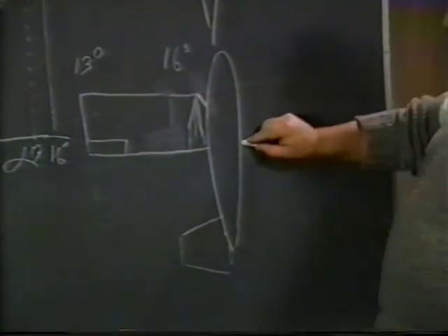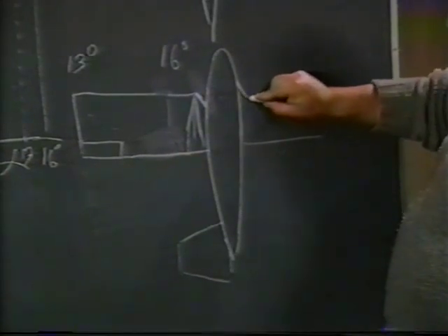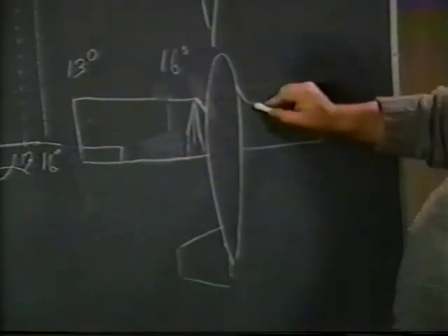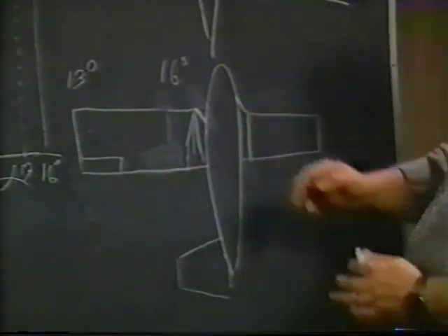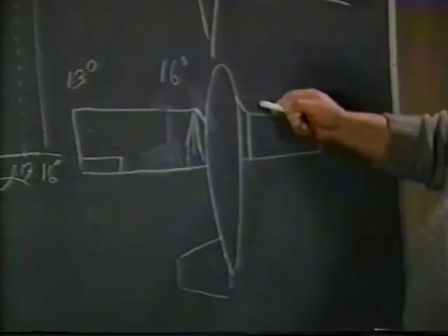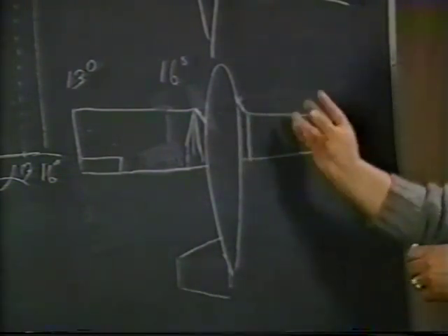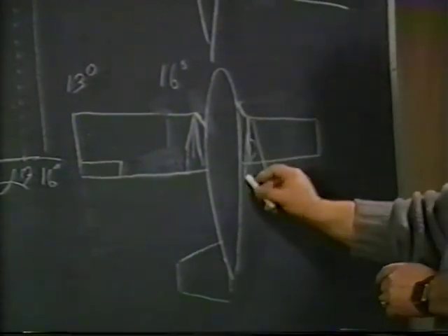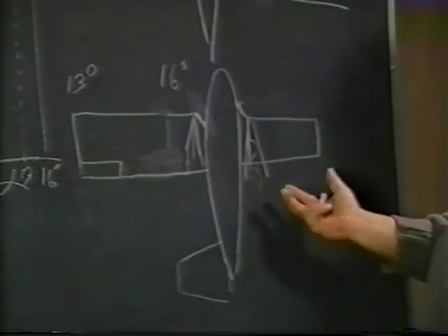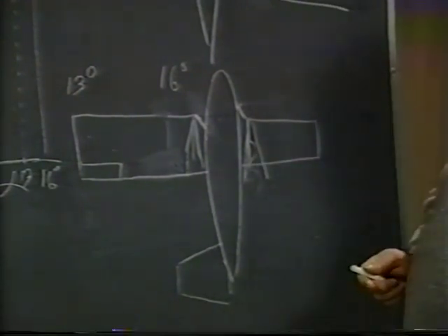Now, another way of doing the thing in reverse, and you'll see this on several airplanes, where they go the opposite way. They put a swept forward portion on the wing, or the wing fillet itself. Now, this leading edge sweeping forward does the same thing. It causes the air to roll over, come over the top, and roll in here, make a vortex, and as this swirling air rolls over the wing, it actually will trigger a stall to begin in that region.